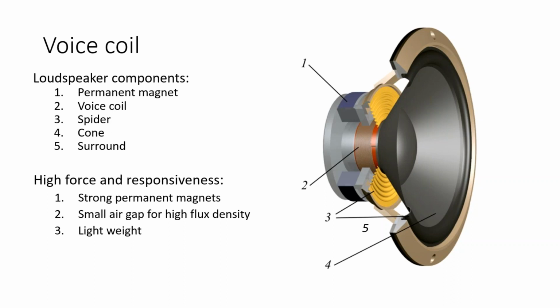The question one might ask is, why do loudspeakers and voice coils use permanent magnets as a fixed component, whereas the voice coil is a component that moves? And the answer is quite simple. You simply have to keep the weight of the moving components very low to maintain high and quick responsiveness of your system with a high frequency input signal.